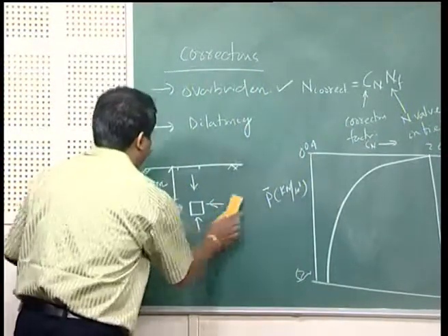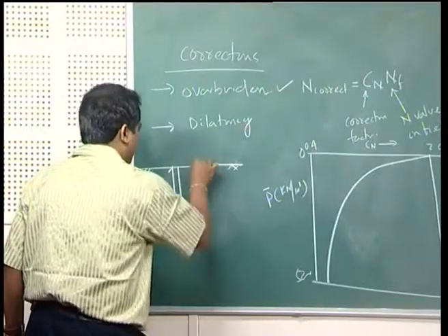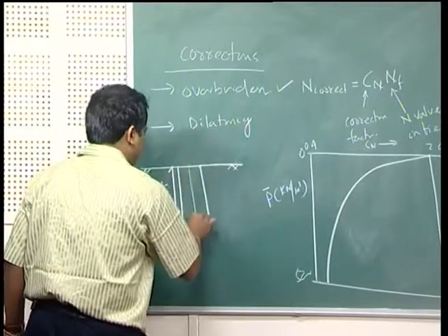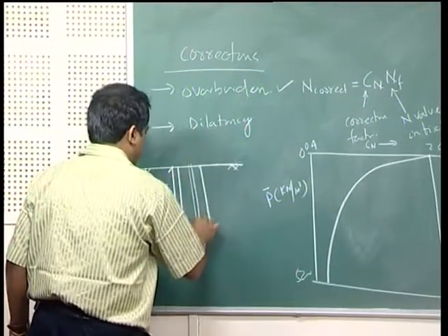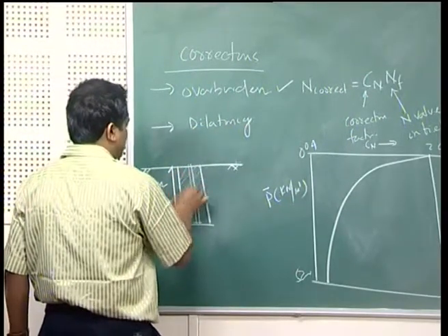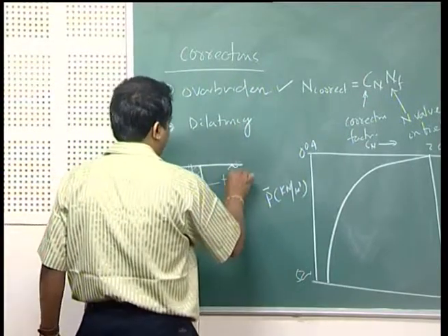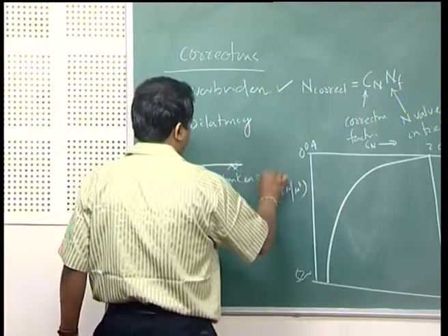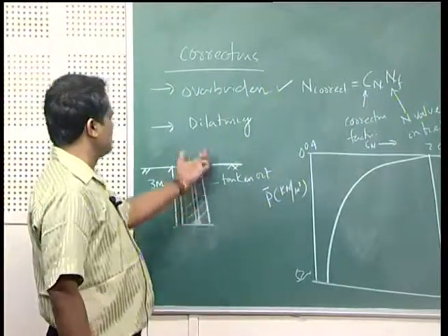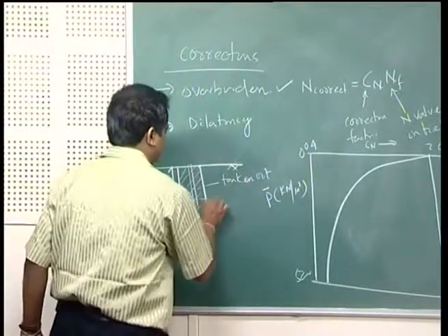The moment at 3 meter depth you make the borehole and measure the SPT penetration blows, what will happen? The soil is taken out from the borehole up to 3 meter, so the overburden is lost.